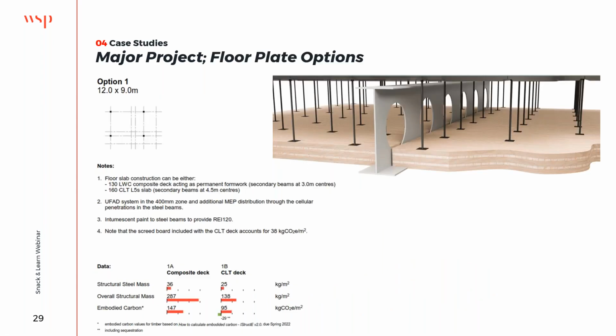However, following that study, we then had a review of the structural zones, the floor to ceiling. It's obviously 1 million square foot of office space, so therefore there was quite a large distance from the center of the building to the windows. So we wanted to maximize the floor to ceiling. So what we did is look at incorporating the structural and MEP zone together, and utilizing a UFAD system, place the CLT on the bottom flange, holes through the beams, and pushed air from the risers out.